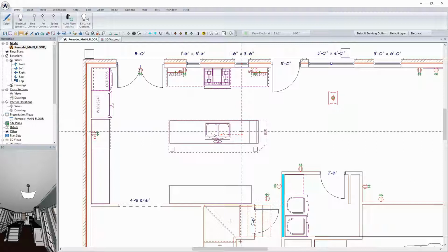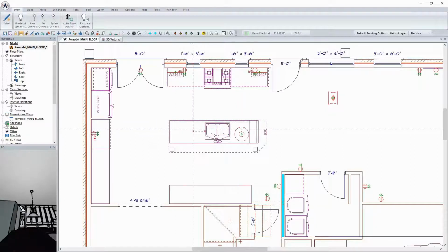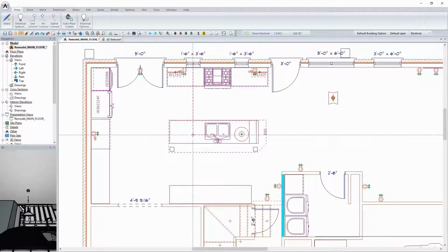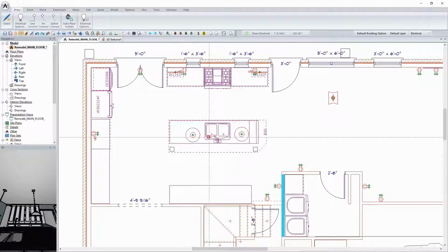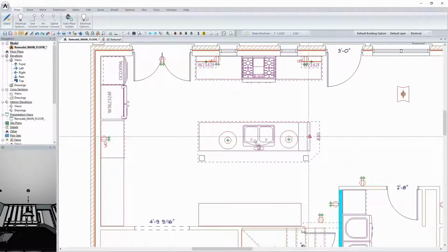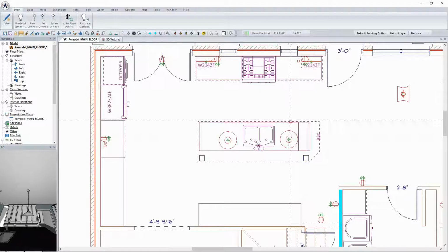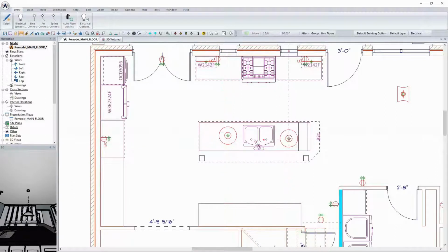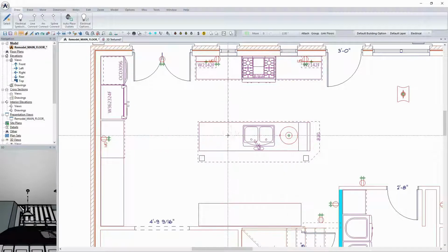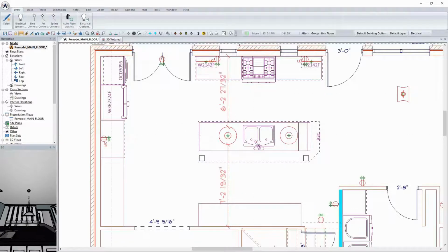One of the things that we did with the design is we really did line the light fixtures up with the windows themselves. We were trying to get some sort of symmetry as far as that goes. With the projection snap on, you'll be able to set that up. You can see how the line finds the center of objects. Then you could move them or edit them to where you want them exactly. But the projection snap allowed me to find the center line of the window, which is the key here.